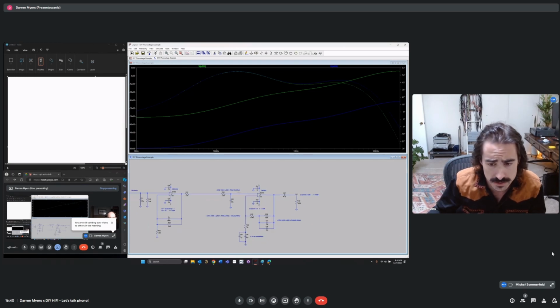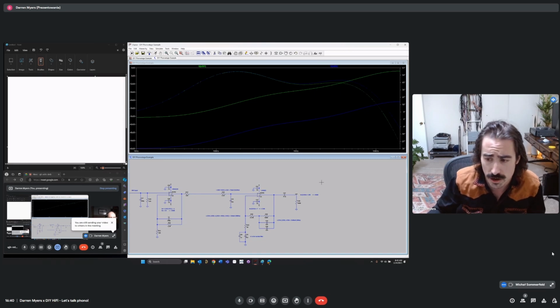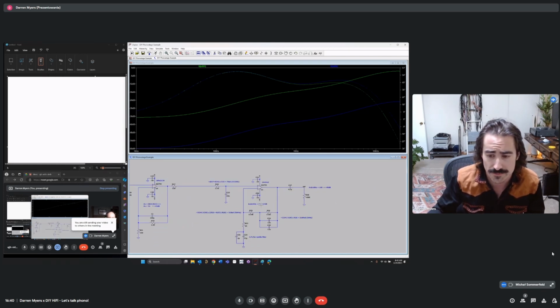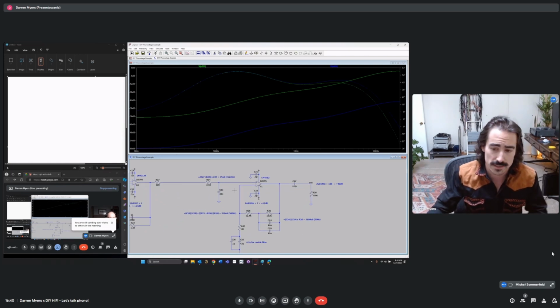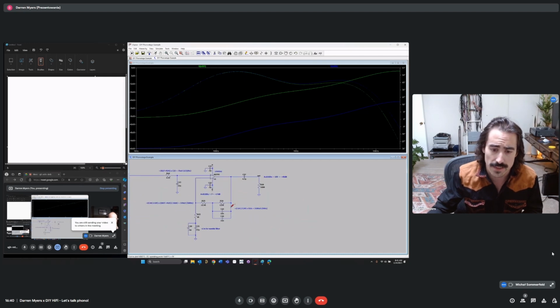So now what we need to do is apply overall 40 dB at 1 kilohertz. So far we've applied 23 dB, which means that we have 17 dB left to apply in the second stage. So moving on, we discussed the passive element here, the passive time constant, and then moving on to the last stage, we are.